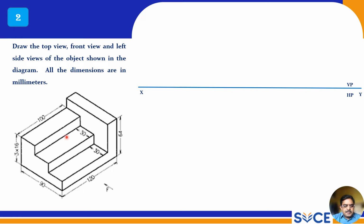Draw xy reference line, and 120 mm is visible, and then 64 mm towards upwards, right? So this is 64 mm, and then this is 120 minus 100, this will be 20 mm, and then you have to come down, right? There are three steps of height 16 mm each, right? So 64 minus 3 into 16, so that much you have to come down, right? So up to here you can come down. So this length is 16 mm now, right?